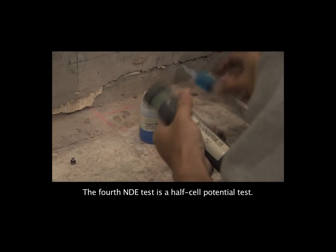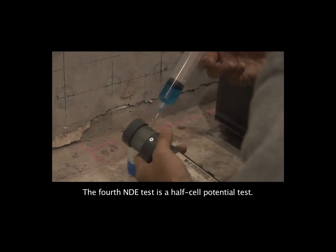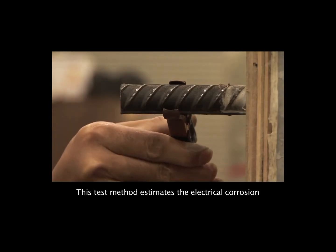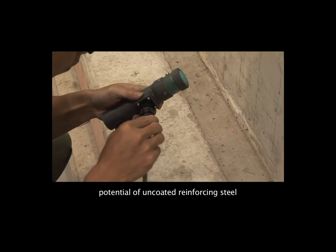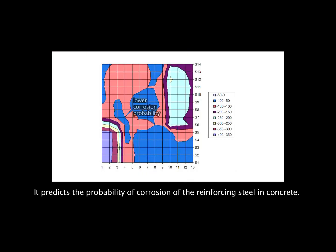The 4th NDE test is a half-cell potential test. This test method estimates the electrical corrosion potential of uncoated reinforcing steel in field and laboratory concrete. It predicts the probability of corrosion of the reinforcing steel in concrete.